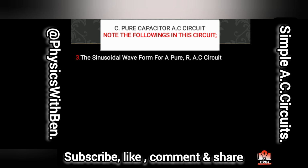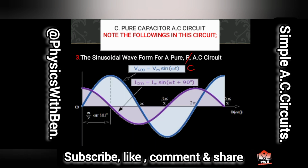The examiners may ask you to draw the sinusoidal waveform for a pure capacitor. This is not R, for a pure capacitor. And this is the sinusoidal waveform. They are out of phase. In this, the purple line is leading. So it means that in this circuit, the current leads and the voltage lags.